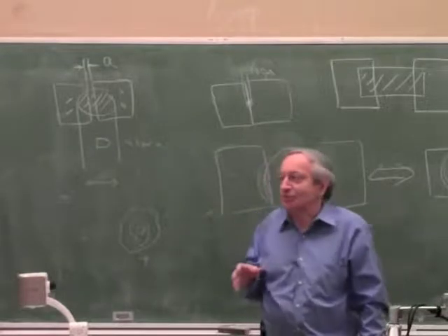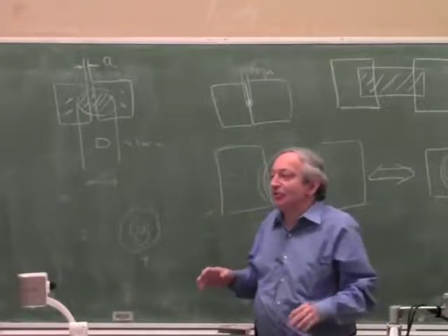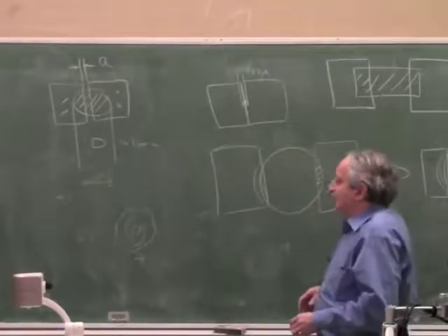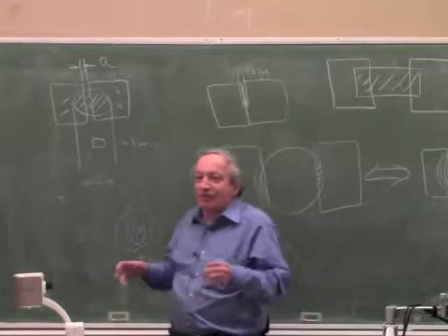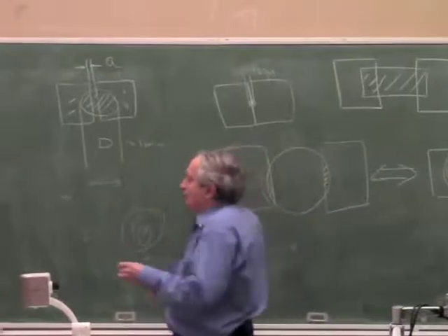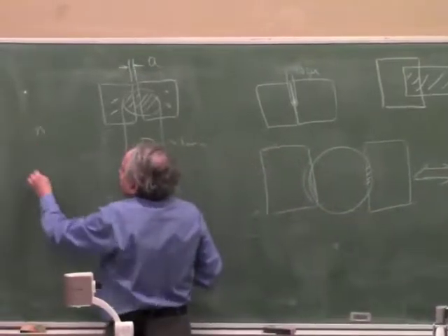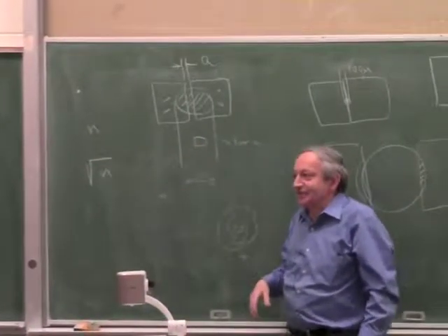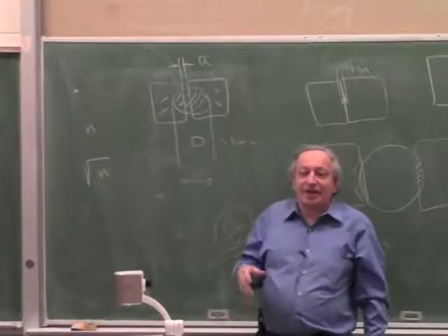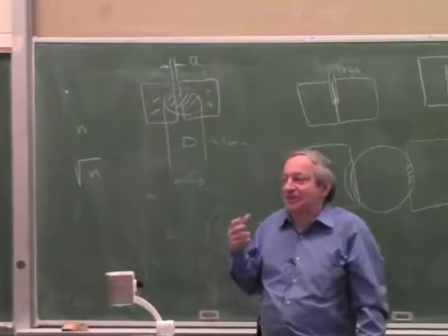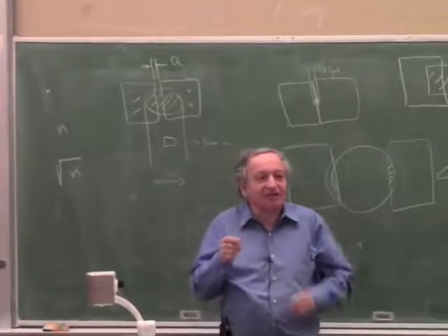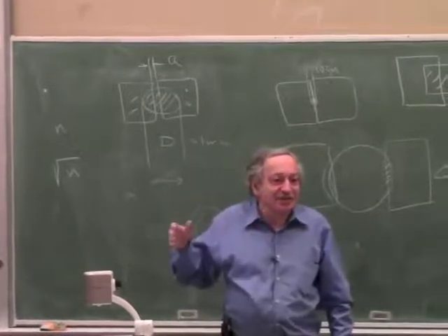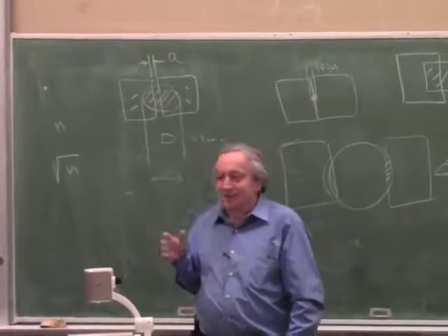And this is a principle which is true for all sensors. The more you average, the more accurate you get, because you know from theory of errors, if you have a lot of random errors and you average n values, the accuracy improves by the square root of n. And you should have learned that in some course in statistics. Okay? So in an LVDT, without thinking, you have averaging. If an LVDT has many turns, the signal is a sum of signals from hundreds of turns. You get averaging. That's one reason it's good.